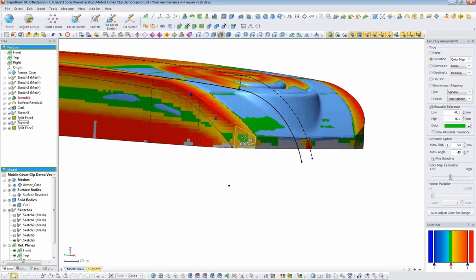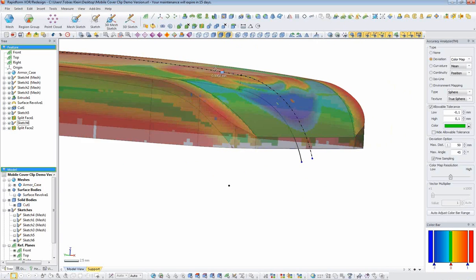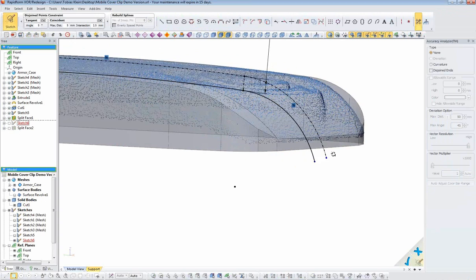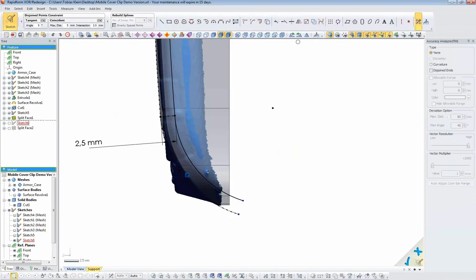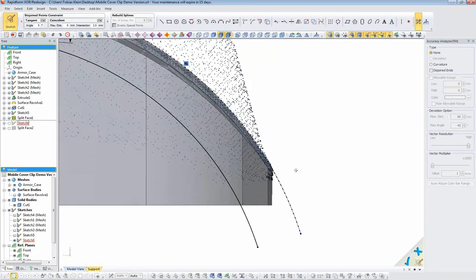But we have another face here. So some green area around here. So if you have a look at the transparency, here is also some line straight through this face. So we need another face. We can define that from this sketch as well. So we have this corner. We can use that corner and project it to that sketch, and then use a horizontal line to split that face actually. So I will just use that face.